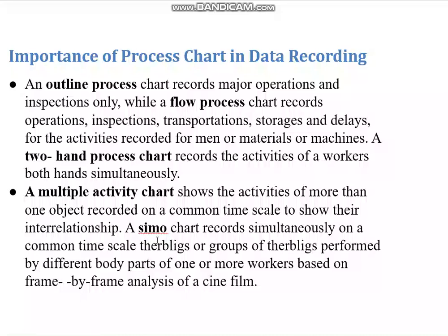We will be studying all these things in detail. Now this is only some outline. A SIMO chart records simultaneously on a common time scale the therbligs or group of therbligs performed by different body parts of one or more workers, based on frame by frame analysis of a film.